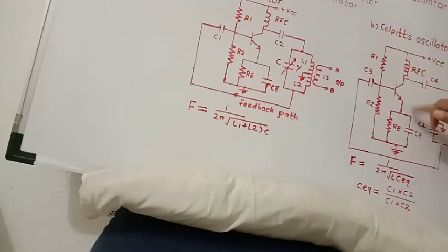That means when the transistor is in conducting state, the AC current flows, and this AC current is passed through the capacitor and does not pass to the ground. So this RF coil prevents AC from passing through it to the ground. It prevents short circuit for AC, and this AC is passed from collector to the tank circuit through capacitor C4.